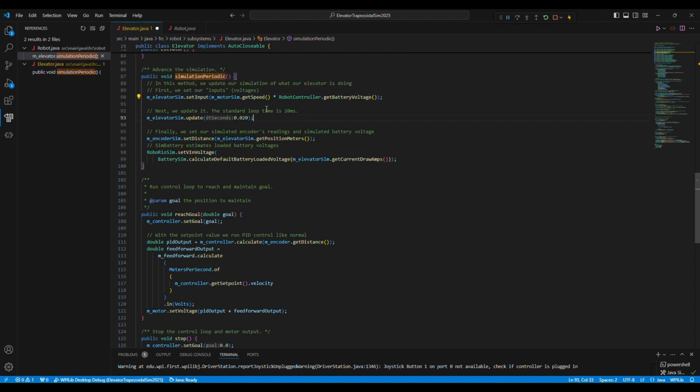We're looking for the voltage that's going to be applied to the motors. So we have to call robotcontroller.getBatteryVoltage to give us the battery voltage, to multiply by 0.5 to get us back our 6 volts here. And the reason why this is important is because this set voltage, again, it strips out the actual voltage. That's why we can't pass a voltage directly back up to here. Whenever you're using a PWM port, there is no voltage conveyed.